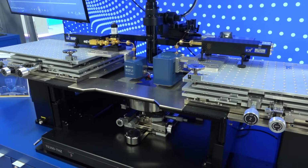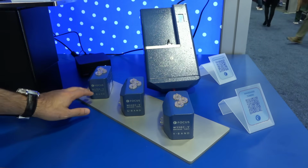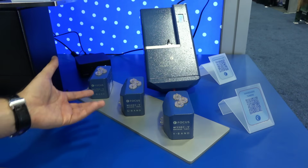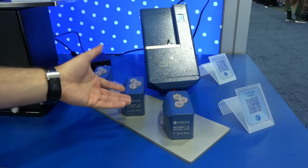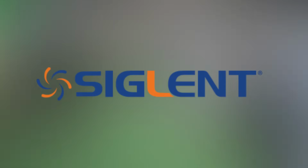It's an impressive setup. So here are a few of these focused microwave tuners, covering D-band, G-band, and Y-band. And one of the cool things about these is that they do have built-in couplers. Normally when you have these kind of tuners, you may have to add a coupler on top, but having them all integrated in one place with connections directly accessible, of course, removes measurement uncertainty, allowing a much more compact measurement.